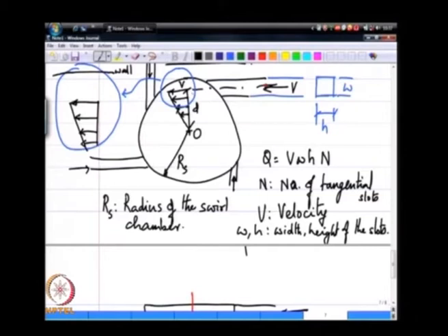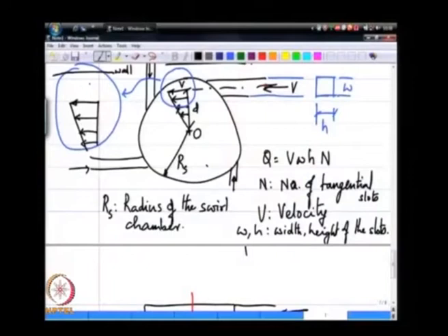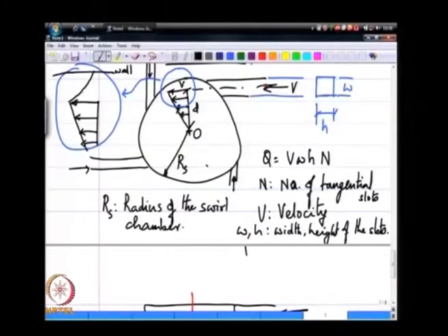Now, from this point where you have this tangential slot coming in to there, you can imagine an invisible rod that is spinning at an angular velocity V over d. So, as far as this part of the fluid is concerned, it is being driven by a rod of diameter 2d or radius d that is spinning with an angular velocity V over d. So, this part of the velocity profile is going to look like a potential swirl.